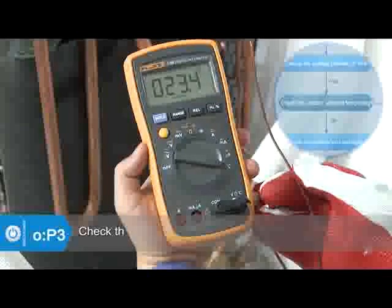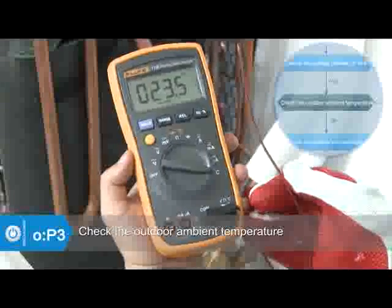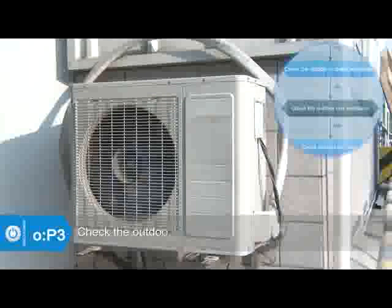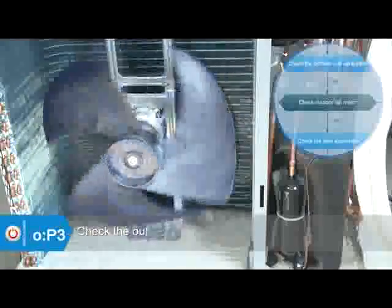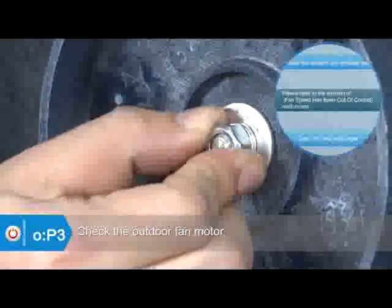If the value is normal, check whether the outdoor ambient temperature is higher than 50 degrees Celsius. If yes, stop the unit. Check if the outdoor unit ventilation is good, and make sure the outdoor unit ventilates well. If ventilation is good, check if the outdoor fan runs properly. Please refer to the solution of fan speed malfunction. Find out the cause and solve troubles.